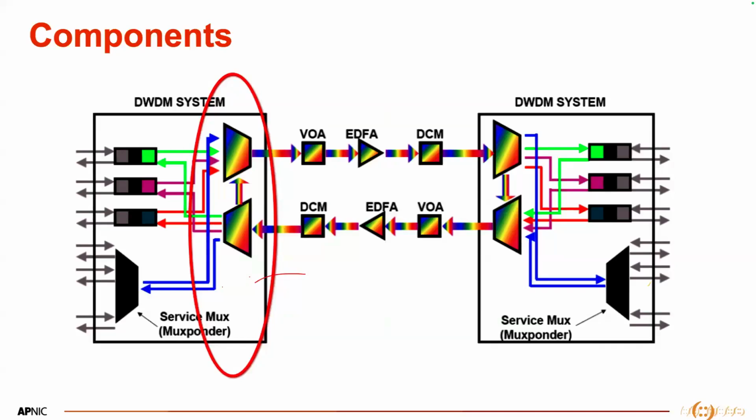fiber type, but for single mode, we basically use the system plain, without any kind of extra modification. We usually use an 80 channel or 96 channel system. And then if we run out of those wavelengths, meaning that we have run out of C band, then we extend to L band and then U band, and this is how it happens. But there is no limitation of the wavelength depending on the fiber type in single mode.